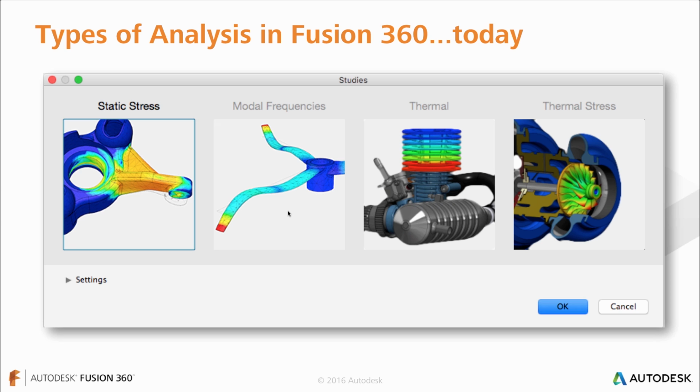There's the ability to do thermal problems, so a lot of electronics, and electronics is a really huge area where they're actually using thermal simulations. Obviously, dissipating heat makes those devices run better, last longer, so that's a big concern. And every single day devices are getting smaller and smaller, and so there's more of a struggle to do that efficiently. Connected to thermal problems are thermal stress. So as bodies heat up or cool down at different rates, you can have pressure building up at interfaces. So if you have 2 different materials heating up, if there's not areas where they can expand freely, there's going to be a lot of pressure at their contact, and that can be a big concern for designers.